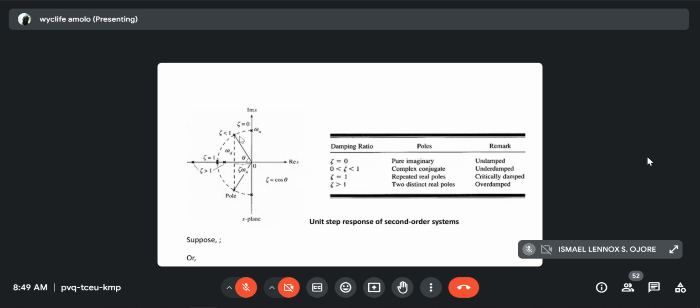And the distance between all this is WD, this Wn is the natural frequency, and that damping value is cos of theta. So if this is the WD and this is the damping term times Wn, this distance, then the angle theta there is given by that value.